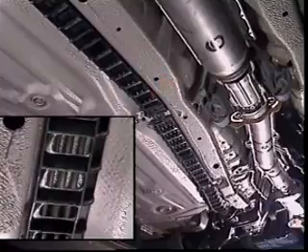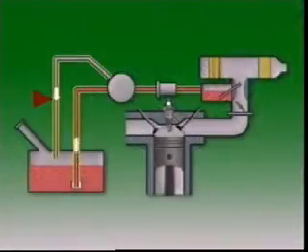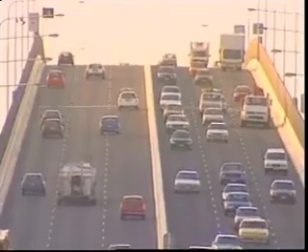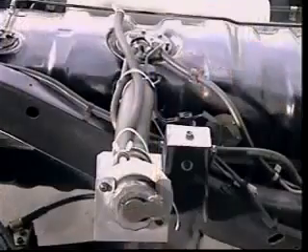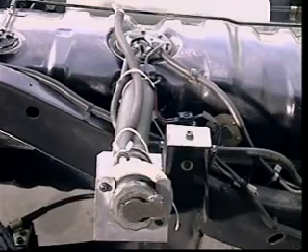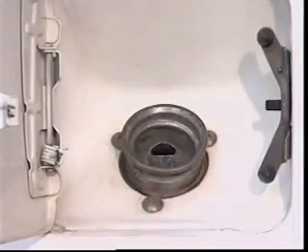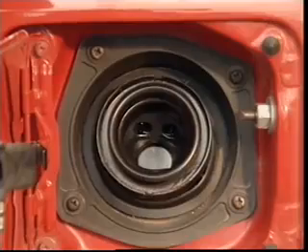Fuel lines are usually made of metal tubing or synthetic materials. A fuel supply line carries fuel from the tank to the engine. A return line may also be provided to allow excess fuel to return to the tank. This helps prevent the formation of vapor that can occur in the fuel supply during hot conditions. The fuel filler is where fuel enters the system. The filler neck is a pipe that extends above the fuel tank. On unleaded petrol vehicles with catalytic converters, the filler neck is designed to prevent leaded fuel being added.